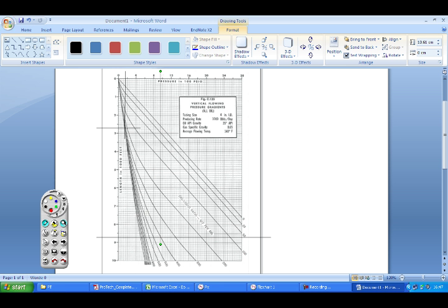So once again, let's start from the other side. If I have my bottom hole pressure at about 960 psi here, then across 6000 feet I will have pressure losses such that at the top of the 6000 feet, in my case at the wellhead, I will have the pressure value of 160 psi, which is exactly what I need.